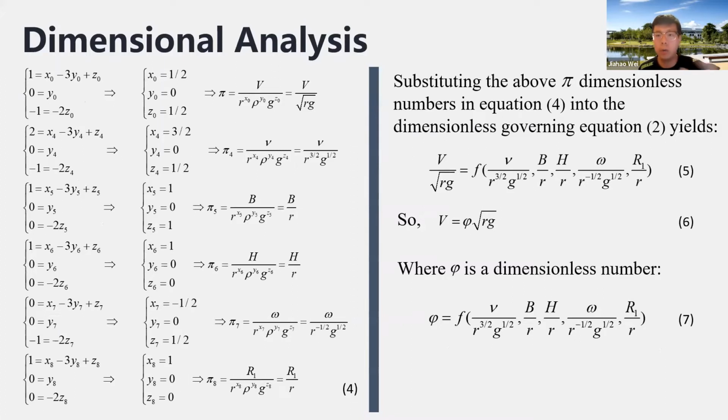So the following equations can be obtained, and then through deduction, equation 6 is the relationship between the average velocity over a cross-section v and the radial size of impellers r, in which the coefficient can be determined by CFD or experiments.